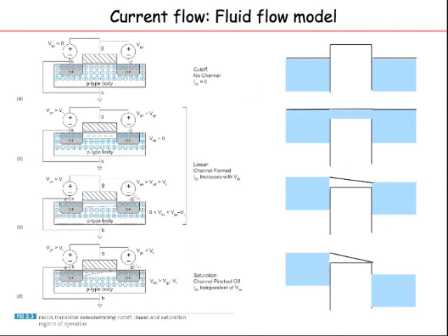So you have the gate voltage, and as you make it bigger and bigger, you are reducing the barrier height. As you make the gate voltage higher compared to the source, you make the gate positive and start attracting electrons, so you start inverting the channel. Once I start inverting the channel, I have a path between the source and the drain, and that's what happens here. You see the gate falls below, and now I have a channel to connect the two reservoirs.